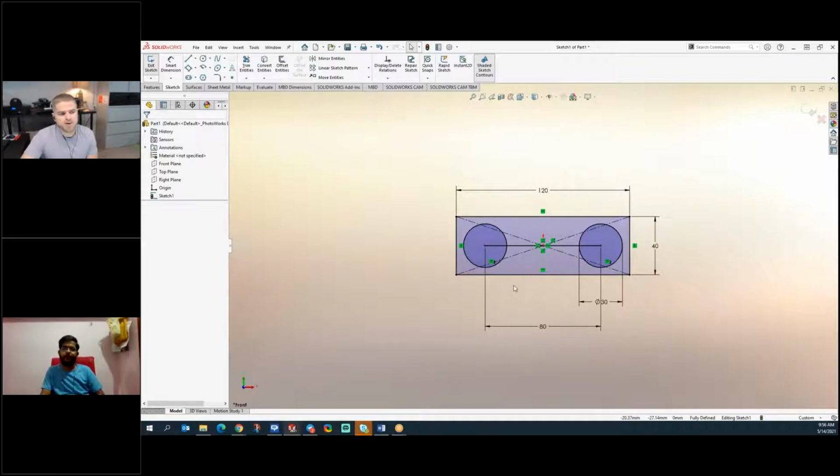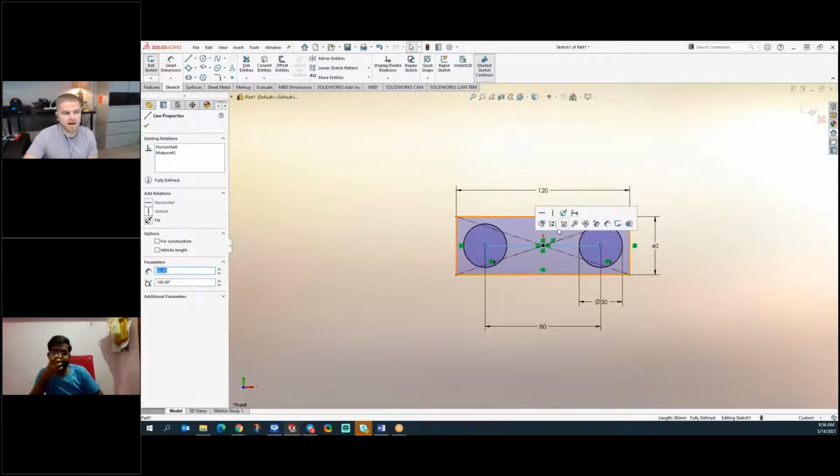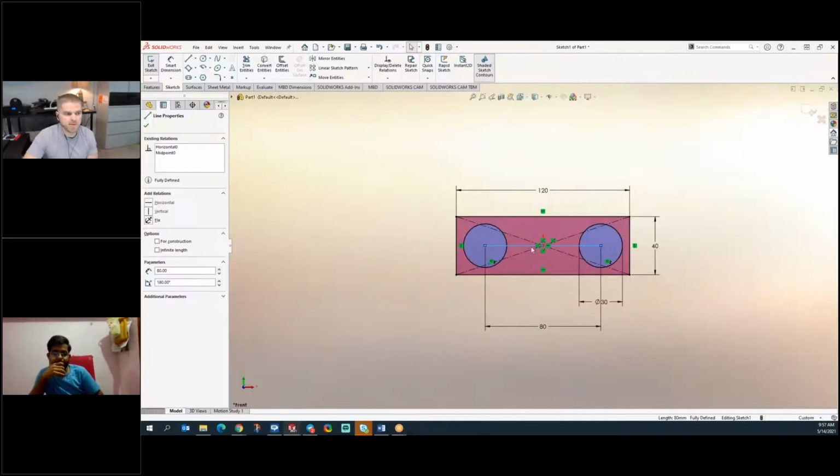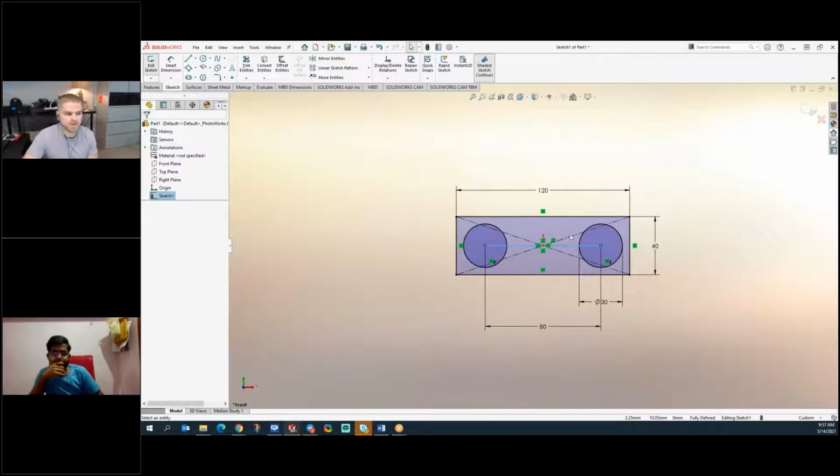There's one more small change before we take this sketch and make it into 3D. This line I used as mostly just a location point for these two circles. I want that line to just be referenced. So if I simply click that line, there's a function here to make that line construction geometry. So when I click that line, I'll just do construction geometry, and then it gets this dashed appearance telling us it's just there for construction.